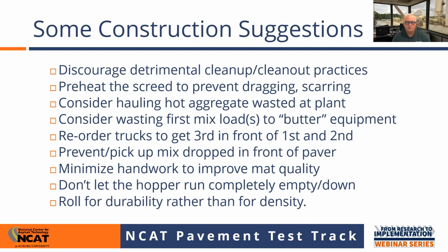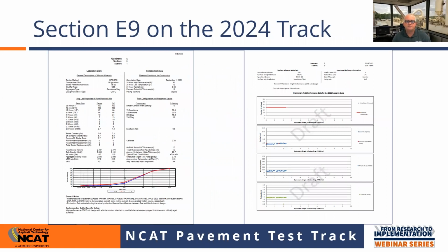And so we have to rethink our design process the way Jim talked about in his part of the presentation, and then we need to step back and do the little things on construction that are going to help us get more years out of these mixes, because we find ourselves sometimes where we have to say, well, we've got to stop using OGFCs while we figure out what we need to do to beef things up a little bit. And OGFC mixes save lives. Reducing road spray saves lives. So we need to make sure that we take the necessary steps to continue to use them.